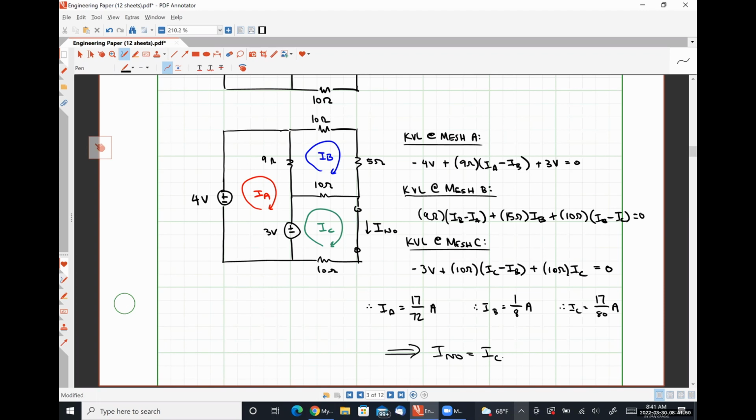The only thing that's really going to do is wind up giving you a negative resistance, which seems scary, but actually isn't really all that big of a thing. All a negative resistance means is that as you increase the voltage, the current decreases, or as you increase the magnitude of the voltage, yeah, the current gets more negative.